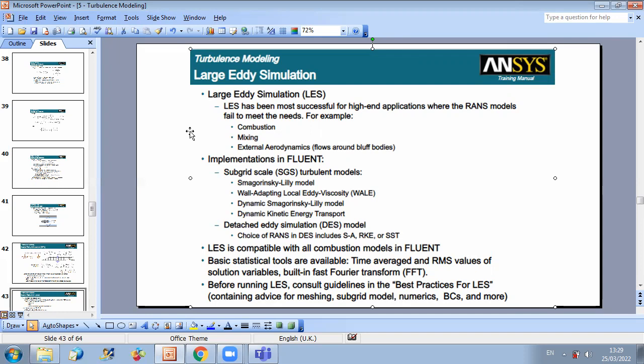So the more complex the turbulence model, the more time you will need, and for each model you should be familiar with its characteristics, in which case it will perform well, and in which case it will present poor results, so you can replace it by another model.